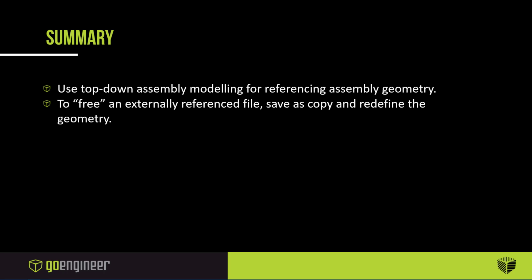Is there a rule of thumb for the max number of parts in an assembly when creating and editing parts in the assembly? I've run into cases where it crashes when I have too many while editing parts with the assembly. So not that I've seen, not a hard number on that, but of course the more relationships that you have, more mates and more parts, the longer the assembly is going to take to resolve. Then it becomes a matter of, do you want to go ahead and use large assembly mode or turn down the detail of your parts, something like that.